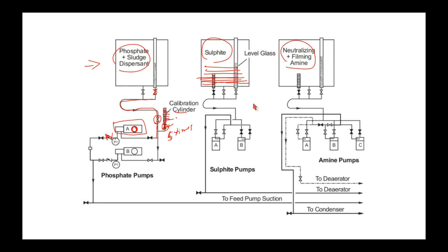And then what we'll do is turn off the pumps, isolate it, and disconnect the hosing, and somebody will come along with a fork truck and take out the old tank, put in a new tank, and then they'll drain what was left over in the old tank into the new tank. You hook it all up, you get it going, you do another drawdown just to verify that it's doing the proper amount. So that's called a drawdown.